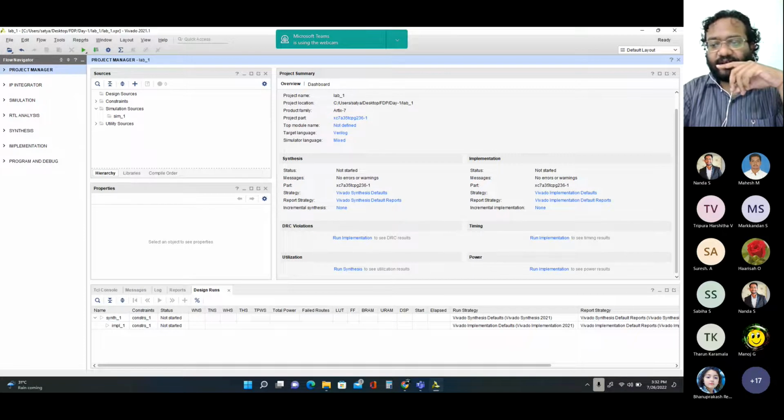Then there will definitely be a mismatch, and the circuit will function inappropriately. Considering this fact, the Vivado tool will not proceed with bitstream generation. So you always need to ensure that you are able to meet the timing with respect to the given clock constraint. Clock constraint means you want your architecture to run at maybe a 100 megahertz clock, or 50 megahertz, or 200 megahertz clock.